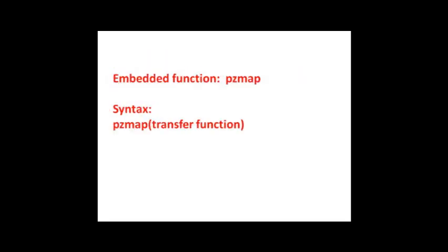Viewer, in order to view the S-plane plot, we need the embedded function pzmap. Pzmap has the syntax pzmap of transfer function, where the transfer function is entered by the earlier mentioned code.